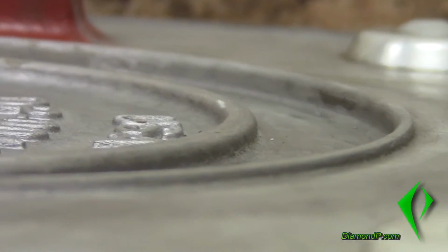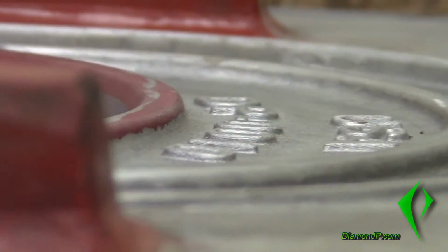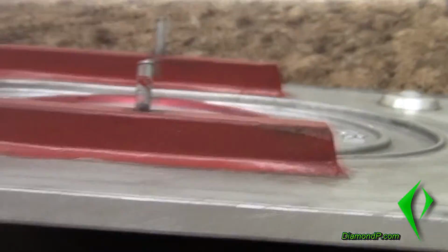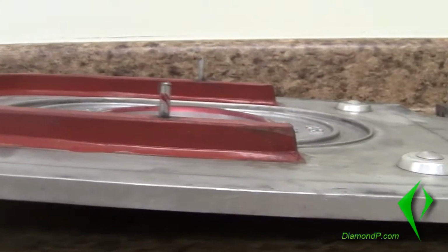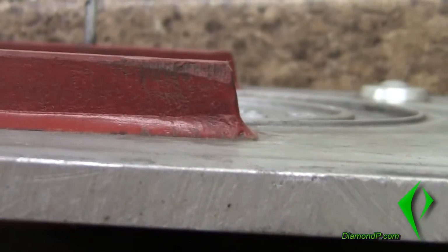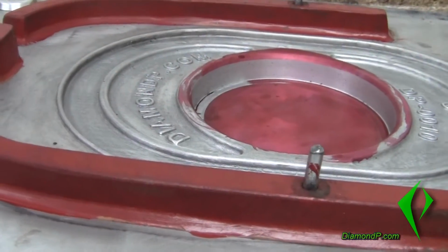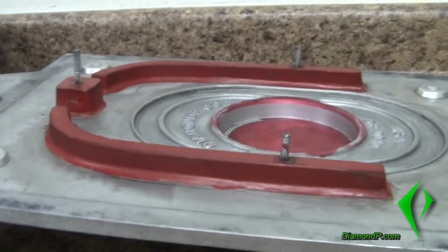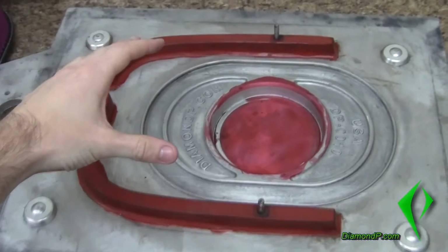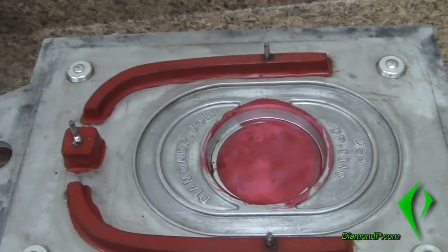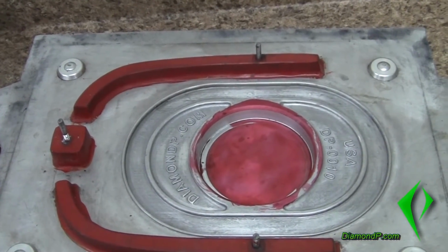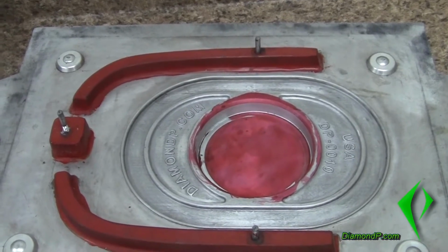They aren't perfectly straight up. They aren't 90 degrees. It's easier to see with the gating around the side. As you can see, there's a lot of angle on them. This is called draft, and draft is used so that when you make the mold and fill this with sand, you can pull the mold off of the pattern and you won't knock any sand loose, or your part won't get stuck.